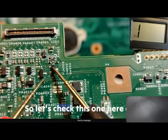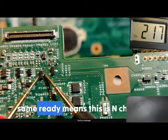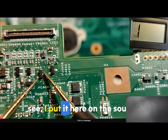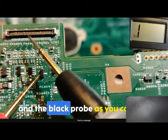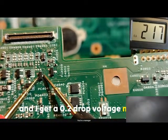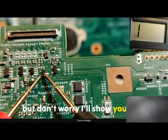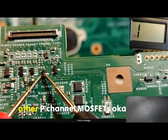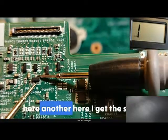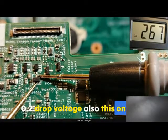So let's check this one here also. One probe here, another here, same reading. Means this is N-channel. Why? Because the red probe, as you can see, I put it here on the source, and the black probe on the drain, and I get a 0.2 drop voltage. Means this is an N-channel MOSFET. But don't worry, I'll show you other P-channel MOSFETs also. Okay, let's check this one, the last one. One probe here, another here, I get the same reading, 0.2 drop voltage. Also this one is N-channel.